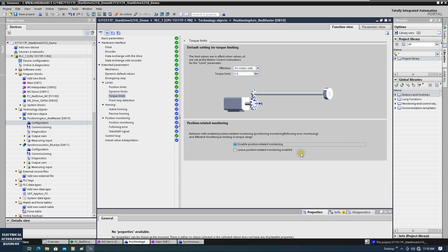If you turn on the monitor, then the system will show the error, and will basically stop the drive. In most cases, we do not want to see this because we limit the torque on purpose. But if your drive has an error, then basically your production line will be stopped, right? This is something wrong, something not happy. So basically, we want to disable the monitoring, even when we limit the precision loop. This is highly recommended: disable the monitor. And then let's go to the programming.